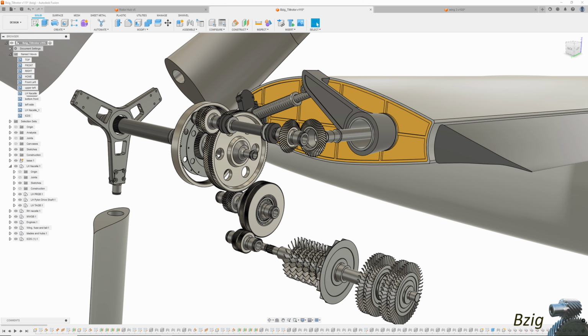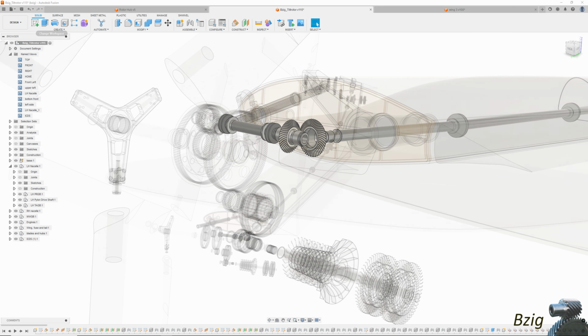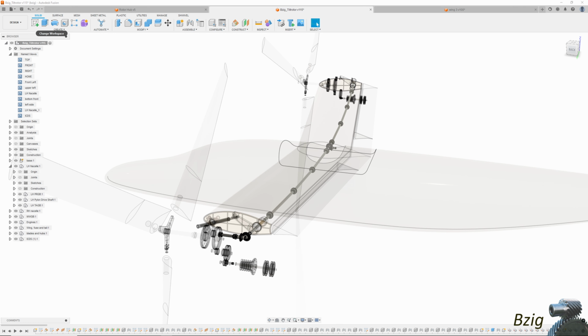Aft of the prop rotor gearboxes are the tilt axis gearboxes. These have an important function during one engine inoperative flight. If the onside engine fails, power is automatically transferred from the good engine side through the tilt axis gearboxes and across the wing interconnect drive shaft to the prop rotor gearbox on the side with the failed engine. This is an important safety feature.